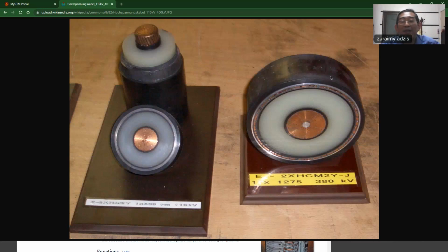If it's fitted underground, and somehow you have access to it, if it's not using semiconductive insulation here, then they will build up voltage, and it will be dangerous for us to handle the insulated part of the cable, because charges are building up there. So it looks simple, cable. The insulation, XLPE, right?